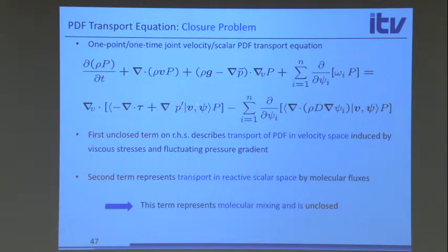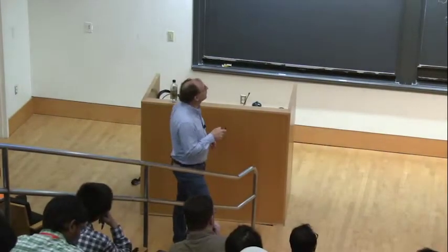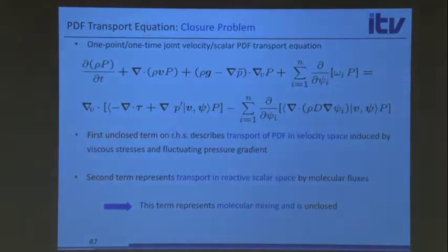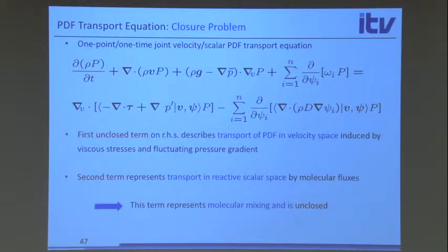But then on the other side, let's not talk about the velocity here, because usually we're interested in scalar PDF. But this here is then the mixing term. This is transport. We said earlier, scalar dissipation is very important. We said fuel and air, they only react if they're mixed on a molecular level. And so this term here, you see this is a diffusion term, that actually represents or describes mixing on a molecular level.